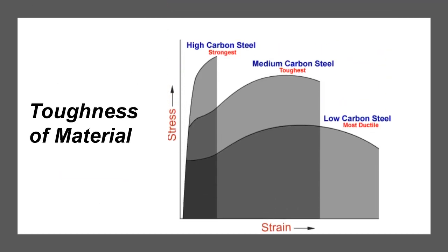Before we get to the fracture mechanics methodology, let's discuss 2 more terms: the toughness of the material and imperfections in fabrication. Toughness is the ability of the material to absorb energy when loaded slowly, and is defined as the energy of mechanical deformation per unit volume prior to fracture. It has a unit of inch-pound force per cubic inch. It can be characterized by the area under a stress-strain curve in a slow tension test.